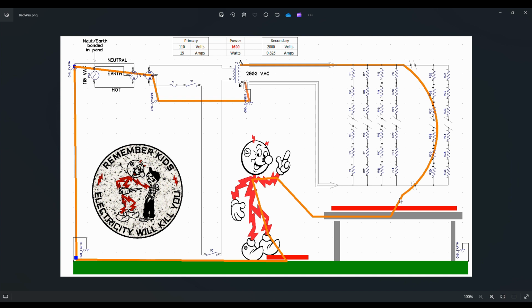That path can include directly onto a conductive table, such as a table made of wood with some moisture content, of course a metal table, through this red rubber conductive pad, through holes and moisture and spills and things like that, or just around the edge of the pad. If you get your wood burning piece and a clamp or something over here at the edge of the pad, it can easily find its way into your table.